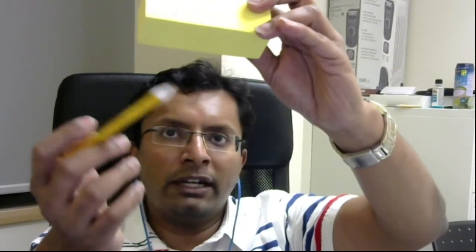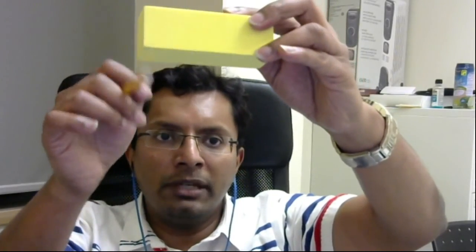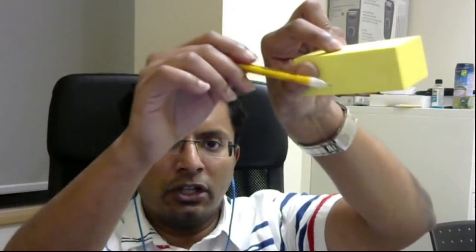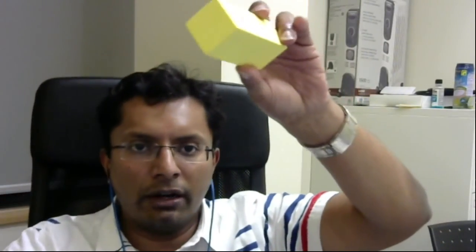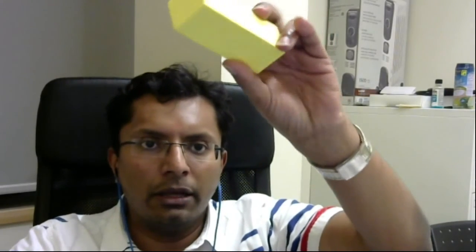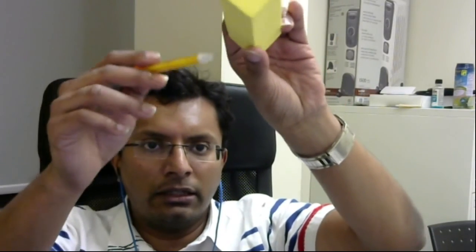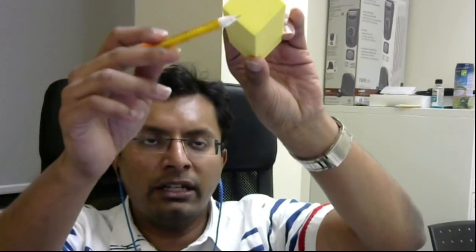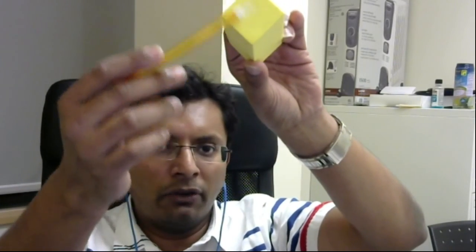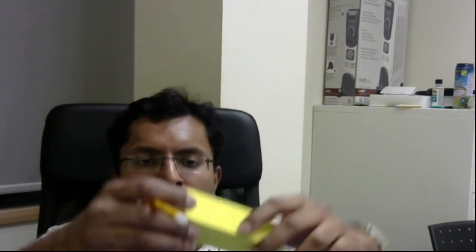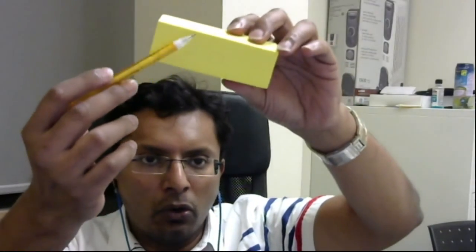And then I'm going to define a reference B, which is going to be this side, and reference C on the back side. So what this does is define a coordinate reference on the shape. Basically, three faces are going to be my three reference surfaces, one face here, one face here, and one face here, which define three perpendicular planes that I can use as my reference starting point to define the true position of the hole.